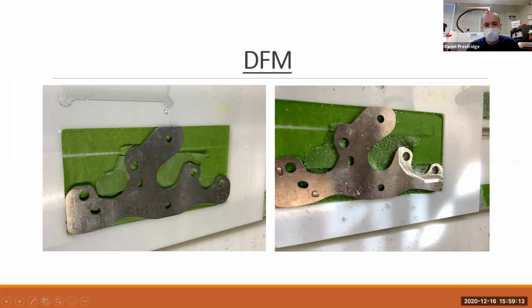So we created a fixture on the bottom where we cut this box out of the high density polyethylene with the straight flute. And then we came in and cut, no, this one had cuts in the corners. And that gave us a box. And the cam that we set up had the origin right here. So after we cut this box, the origin was still set in the exact same spot.